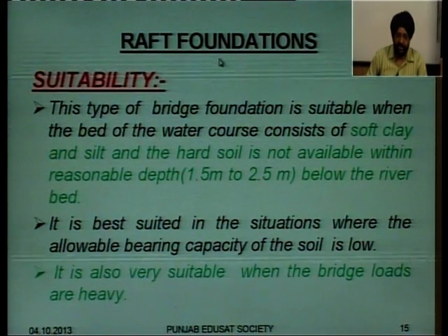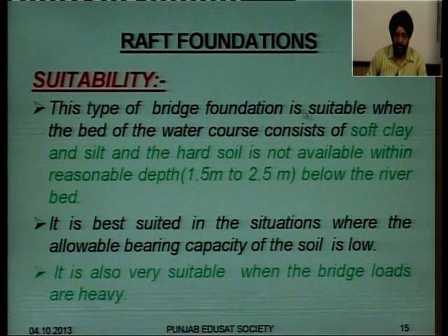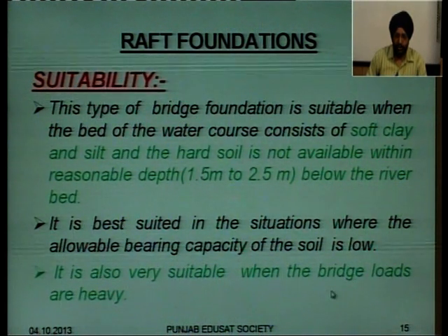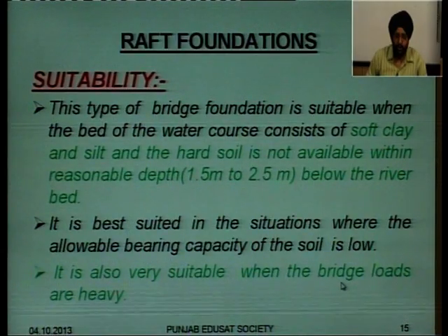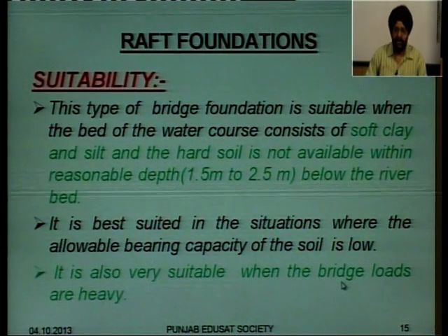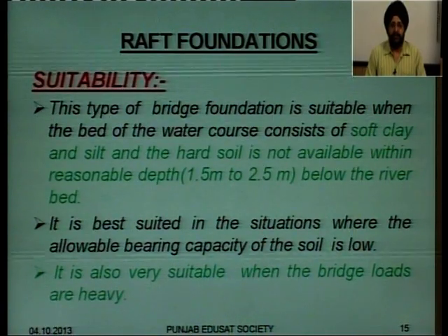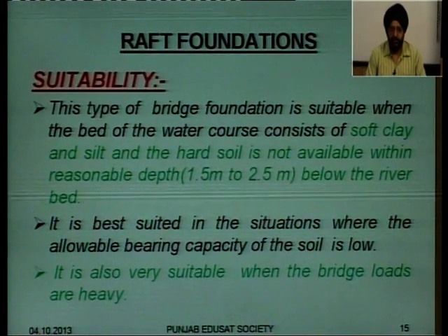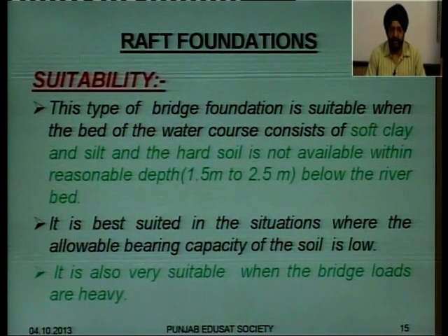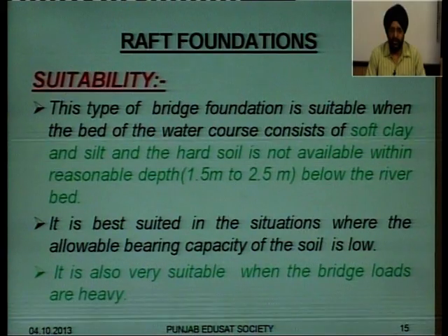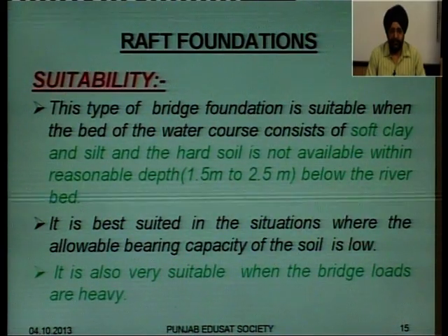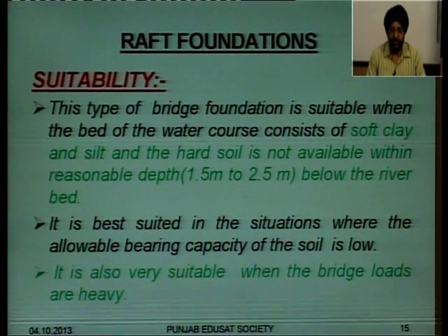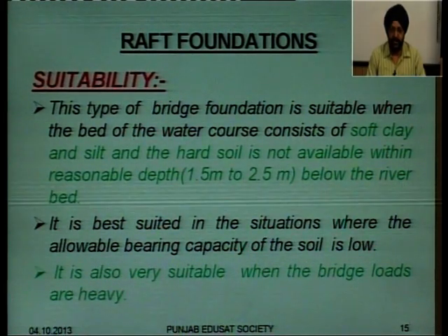But raft foundations can be provided on soft soils having low bearing capacity, and also where the bridge loads are very heavy. So these are very suitable in such cases. We are comparing the previous one and this raft foundation, how their suitability differs, the spread foundations and the raft foundations. Both are shallow foundations, but these are the major differences between them.